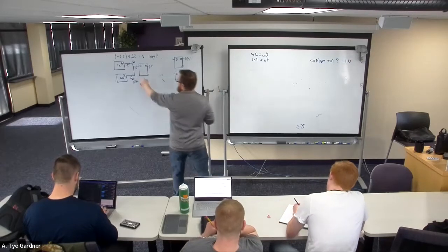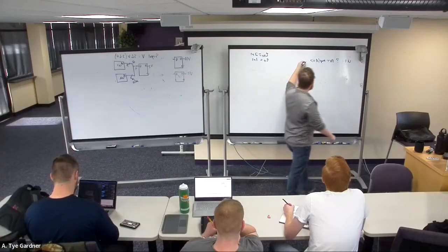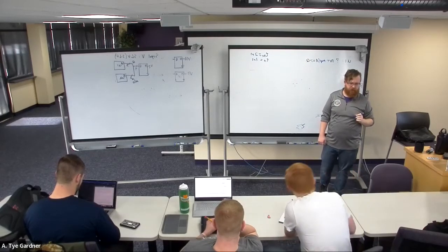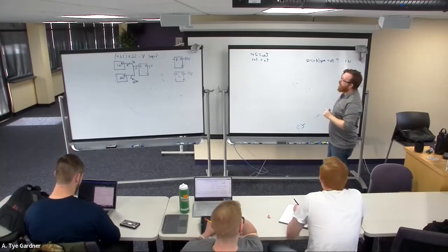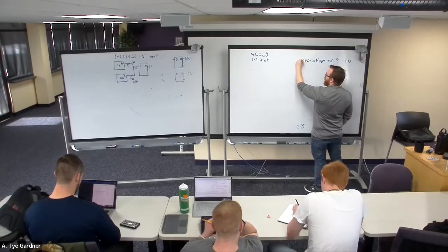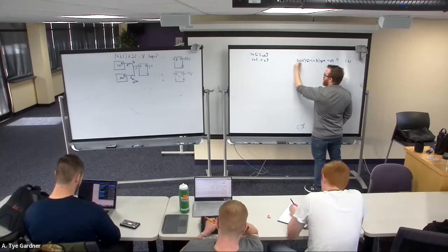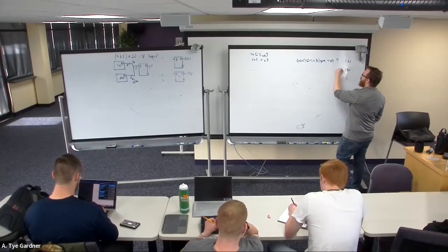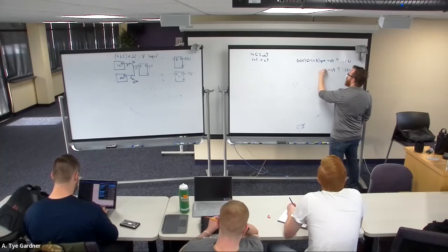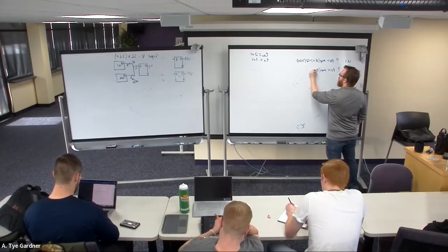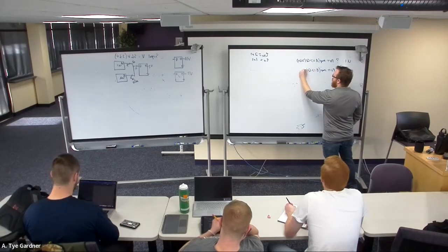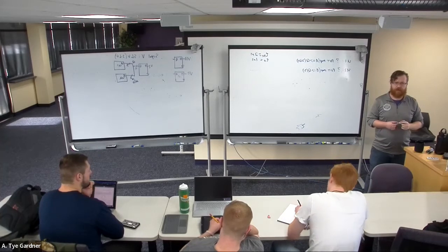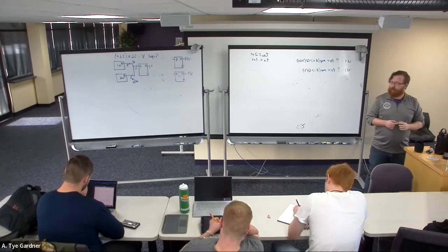So what this is saying is that signal Q needs to connect to A, but not all of Q, right? So what I've drawn here is a bus. So what that's saying is Q2 down to 0. Then when I have my port map for U2, whatever device it is, port map B gets mapped to Q at 3. That's how I split a signal.